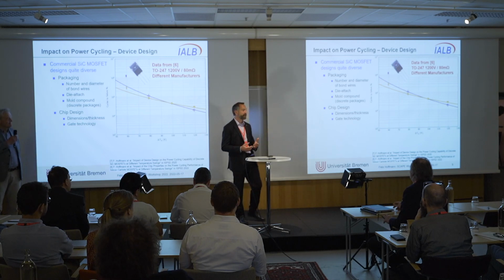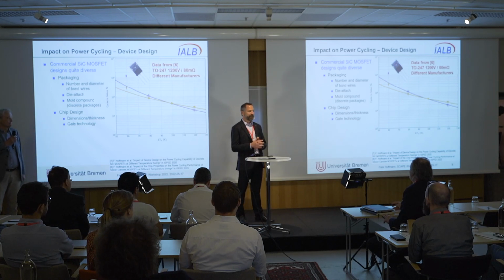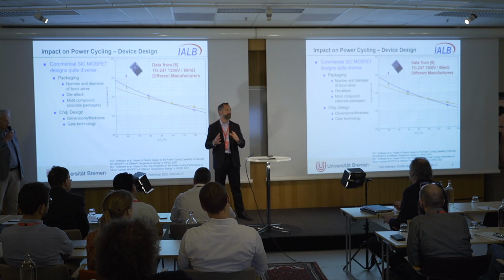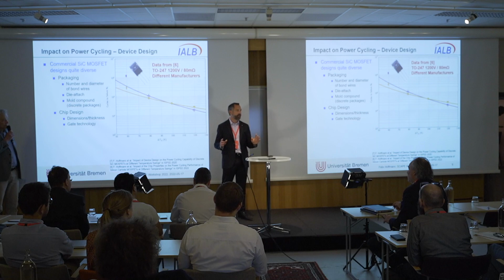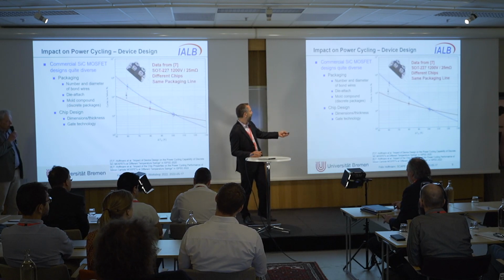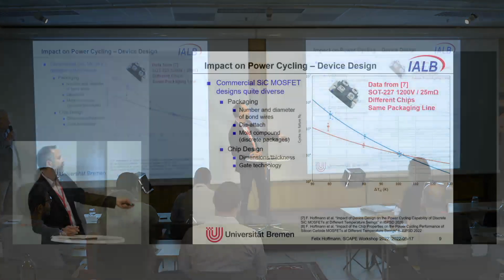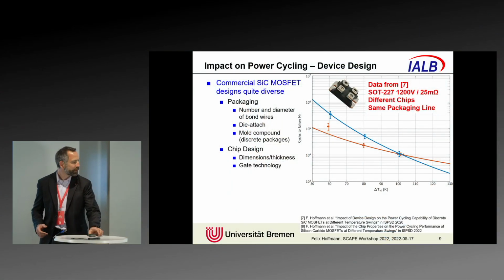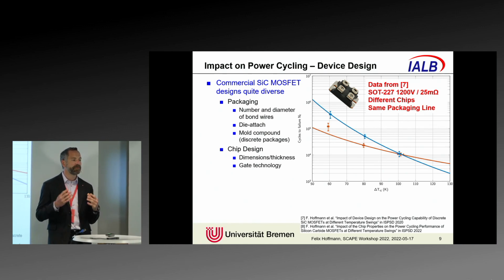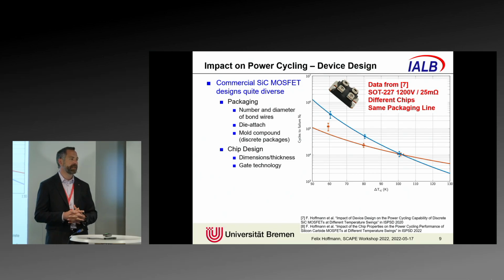For some devices, it might work just fine. We have seen that as well, that you can fit the results for some designs pretty well with a simple Coffin-Manson. You can see it here, on this slide. It works just fine. It's almost absurdly good, this fit. So it just depends on the device design. You need to verify this for your particular design.